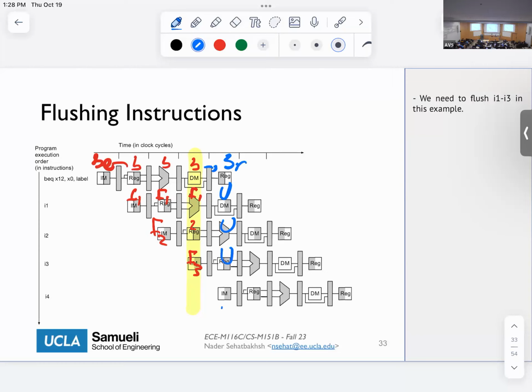And here I'm going to actually fetch the correct instruction. As I said, I'm showing it with IM or something. Okay. So 3 bubbles, a correct instruction in the fetch, and the branch instruction in the write back. That's what we're going to have. So here is finished. The bubbles continue here, and then IM comes here, and at the next cycle, IM plus 1 comes, and so on and so forth, right? So these things continue as usual. All right.